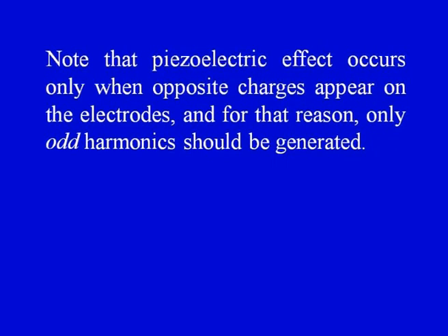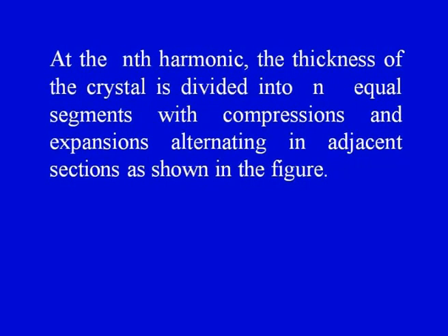Remember, the piezoelectric effect occurs only when opposite charges appear on the two electrodes, and for that reason only odd harmonics should be generated. We know at the nth harmonic, the thickness of the crystal is divided into n equal segments with compressions and expansions alternating in adjacent sections as shown in the figure.